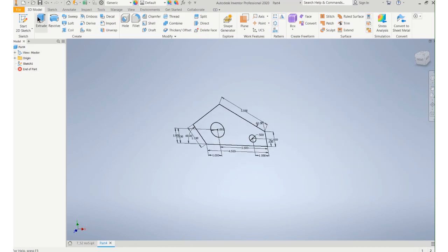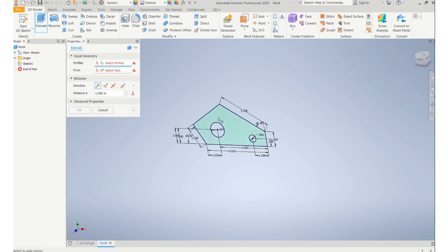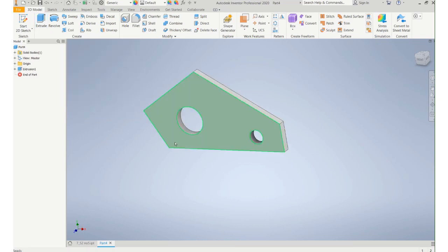And let's go ahead and extrude it. In this case, this is 0.25. Now what happens if you decide you want to edit the sketch after you've already created your extrusion? So we'll go back to our part tree and notice if you put the cursor over there as you run down the part tree, you'll see extrusion 1. I've only done one extrusion, so clearly it's that one.